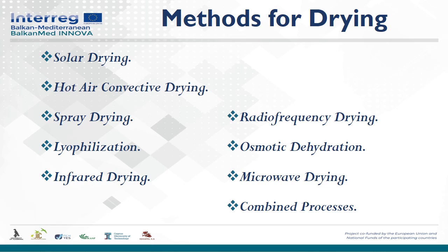Radiofrequency drying. Radio frequency heating addresses directly the product so that its interior is heated faster than its surface. The water is released without overheating or dehydration of the surface. This method allows reaching very low humidity levels of 1 to 2% with minimal impact on quality.